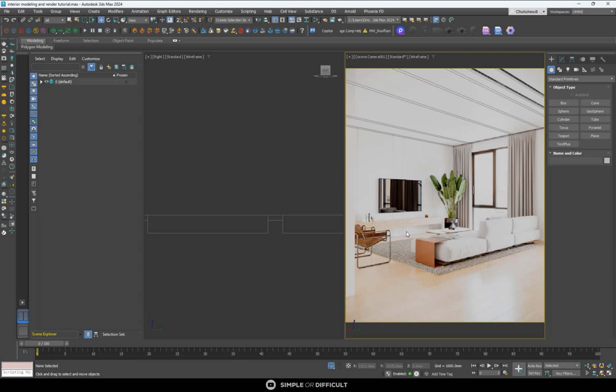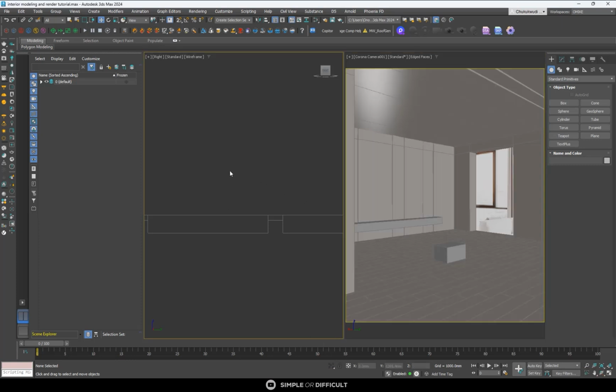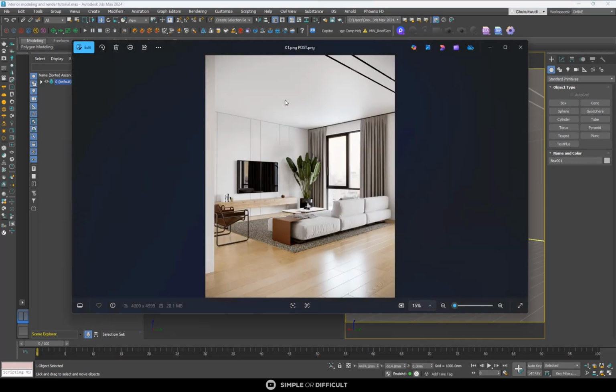So when I hit F3, as you can see, now I'm going to bring everything back. You can see we're already having the scene, right? So what I'm going to do now is create the material for the floor. Every other thing here can be white. Let's look at the image again. It's white, just that this one is a little bit off-white from the normal wall and the ceiling. But you don't really need to do much there, you just need to adjust the color. But the floor, we're going to create this floor.